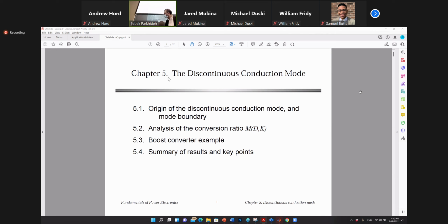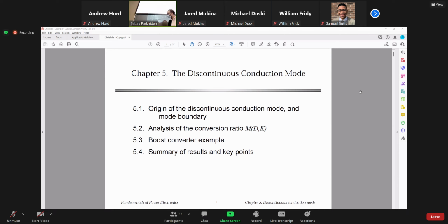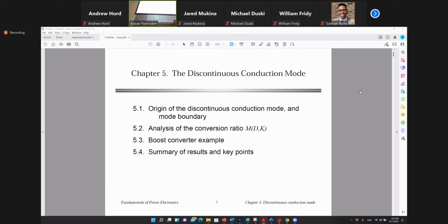And now, this time, you have considered the time that this has been recovered. So now you have your switching losses. Again, as we said, because this is usually the dominant part, we ignore others. And in the book, you have a simple equation, right? And you can calculate the switching losses in MOSFETs. And there is an accompanying diode here. Right? Is that clear?